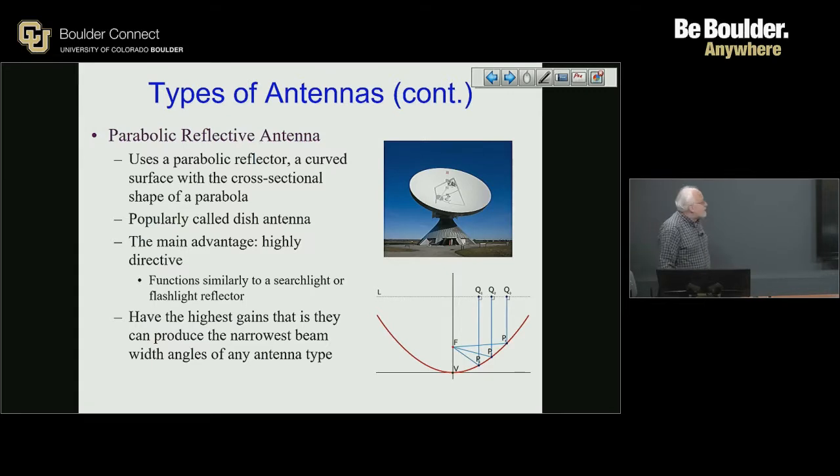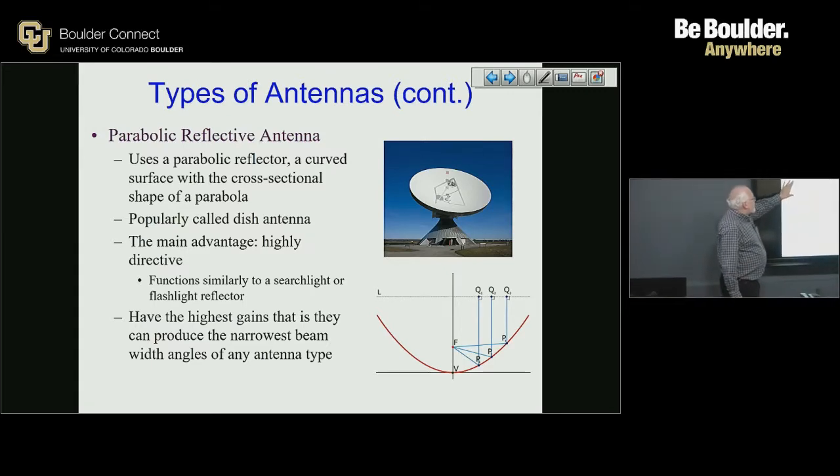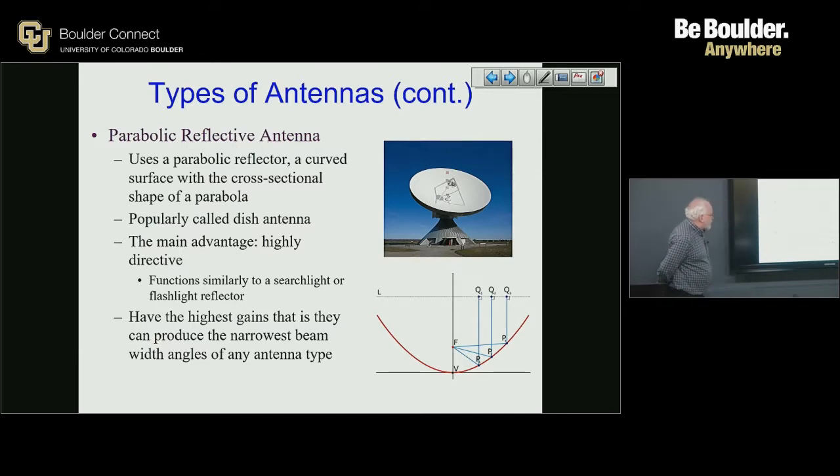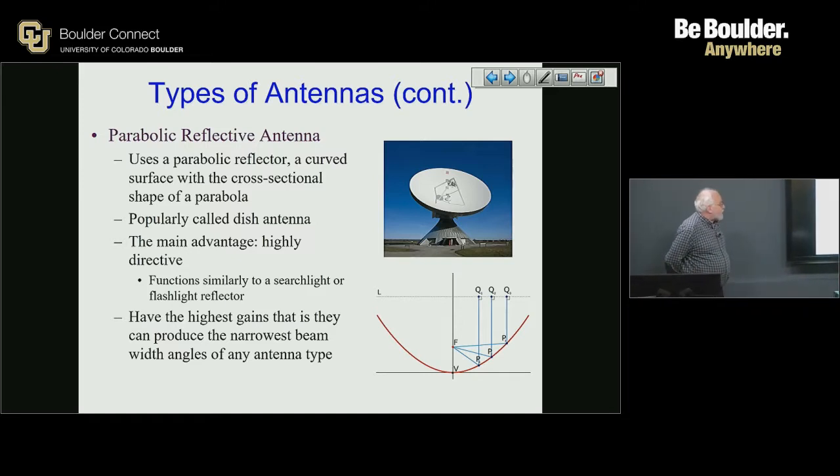Sometimes you'll see parabolic antennas in building-to-building systems. These can have much higher gain. In the house we used to live in, when we first moved there, they didn't have DSL, so I had to have a company called Skybeam come to your house and mount a parabolic dish pointed up at an antenna on a mountain a few miles away. It was actually using the Wi-Fi bands, the radar bands for Wi-Fi. They point that dish up at the antenna, and that dish had about 20 dB of gain.